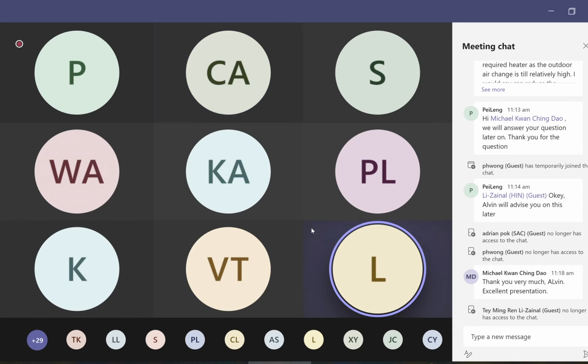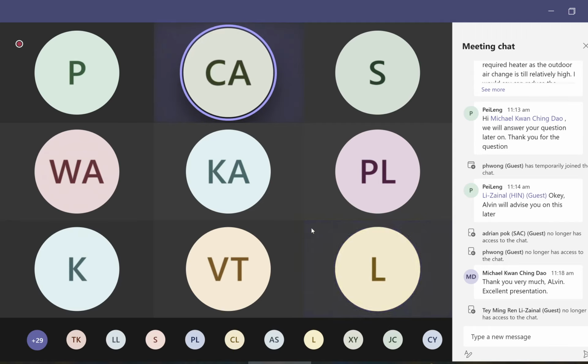But you always have a certain area that is overcooling because the temperature that you set is based on the dew point, the off-coil temperature, either 12 or 14 degrees C. I see. I'm sure there's a fix for this. I just need to understand your design or the schematic better and propose a fix. Maybe add a branch differential pressure controller or a damper to maintain a certain part of your system, especially those nearby to the AHU. Right. So additional pressure control needs to be added in your system. Yeah, this is the answer.